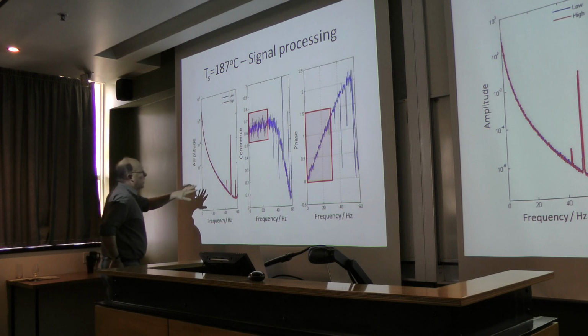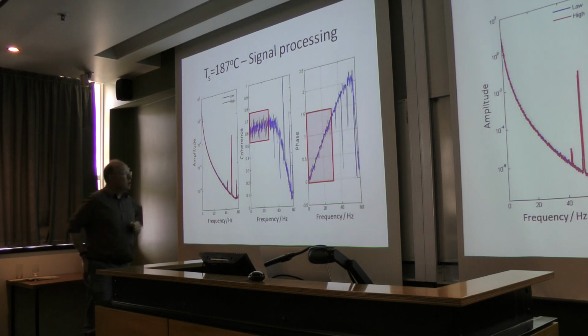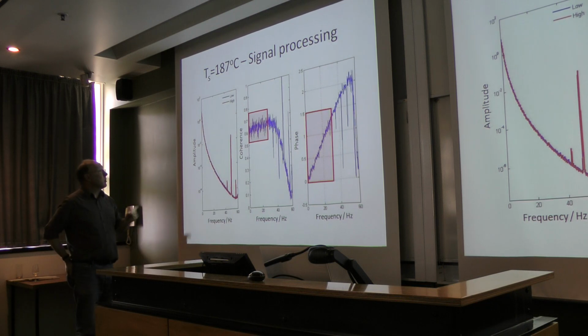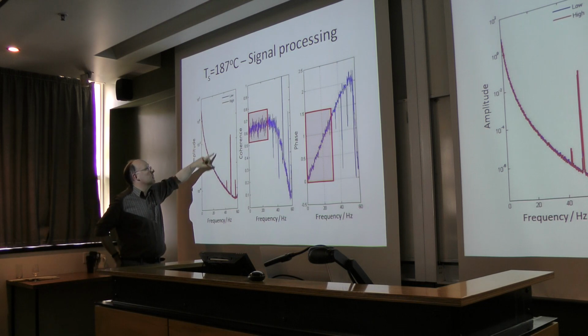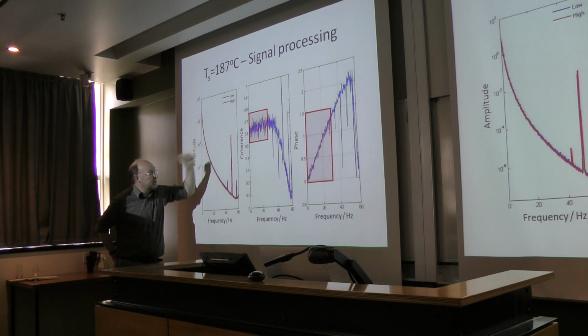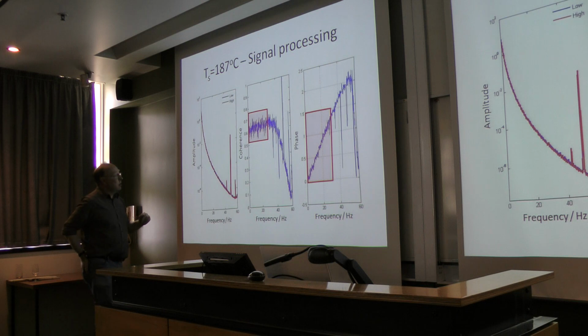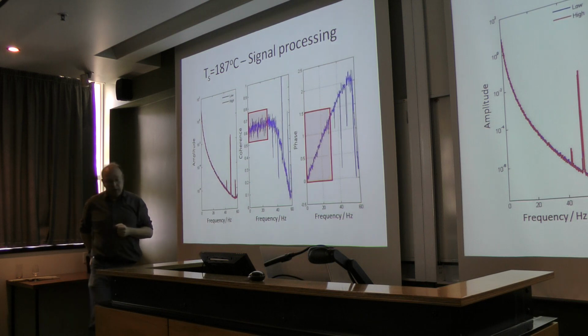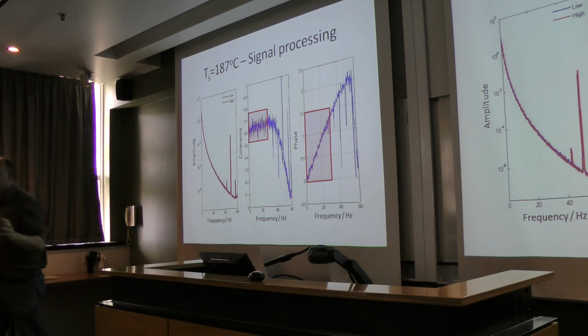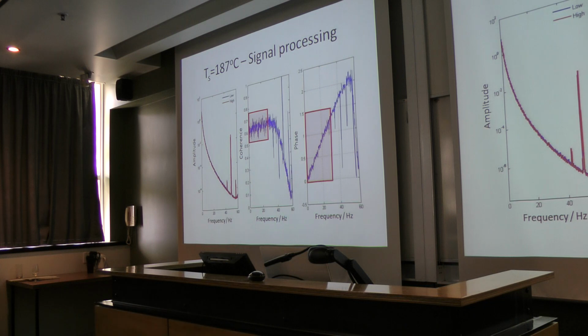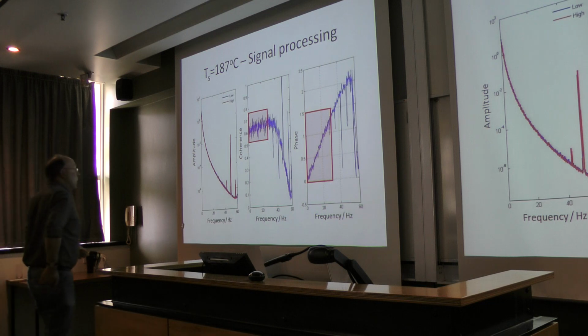And what we've got here is a Fourier transform of the time series. We've got two Fourier transforms here, actually the lower thermocouple and the red one is the higher thermocouple. You've got amplitude versus frequency. I'm not a signal processor by any means. I just think of these in terms of you're representing that time series as a whole load of cosine functions that have amplitudes and wave numbers in there, or frequencies in there.